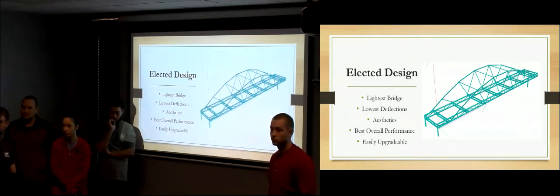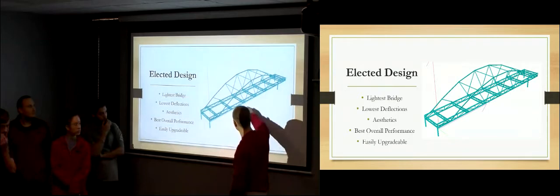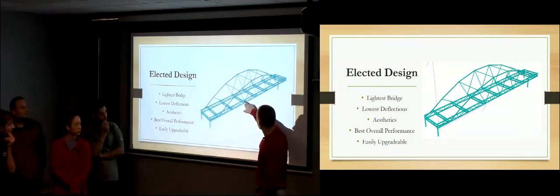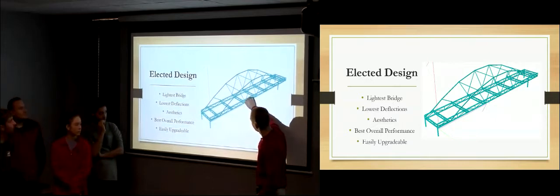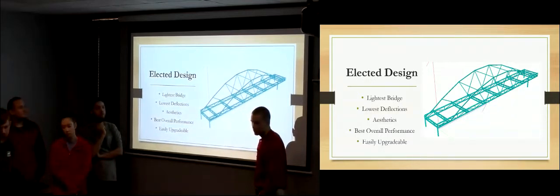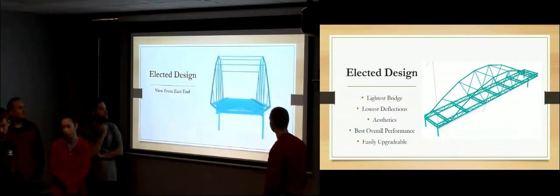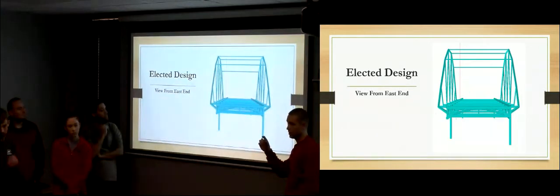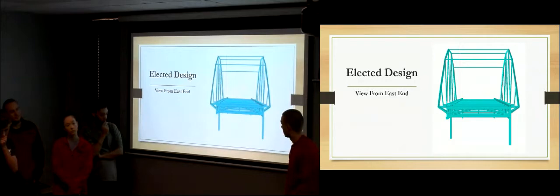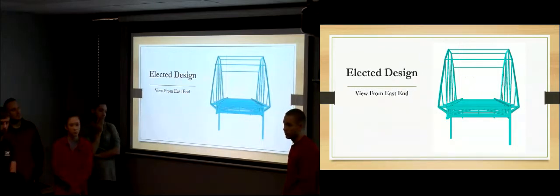How long are your members on your truss? The ones that go up? Yeah, each one of those. Another thing, these little brackets right here will have a male connection, so that'll give me a little extra leeway. They should meet specs with that little extra male connection. I've got basically 4 inches of male connection that I can add on, and I think the longest one we're talking about was like 41 inches long. So do the math, that works out.